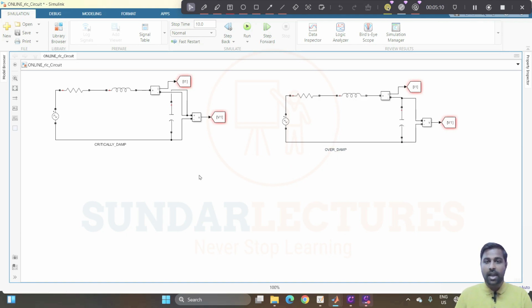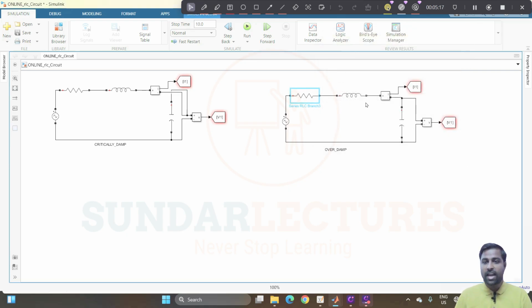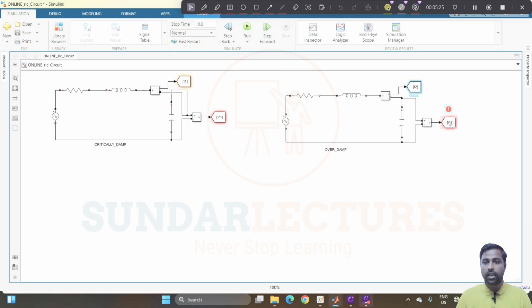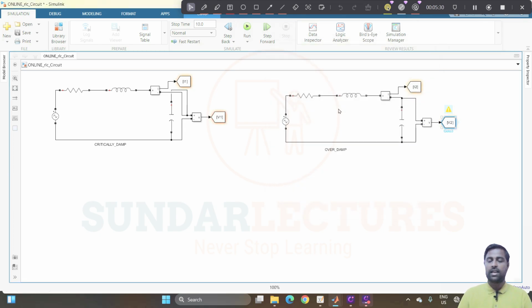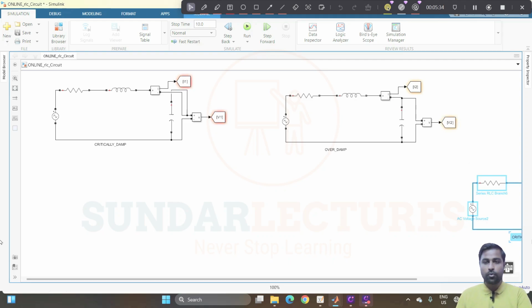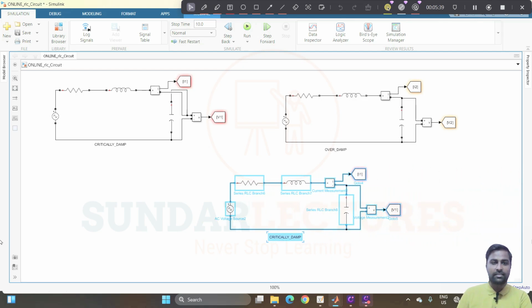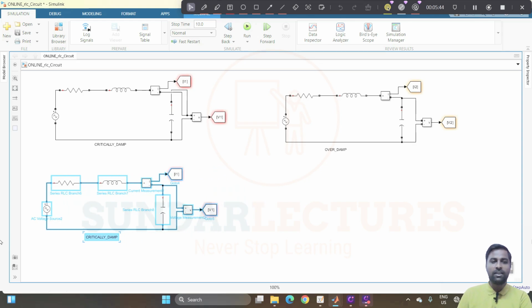this is over damped, and for the over damped, what is the difference? This R has to be 300 ohms, that's all, that is the only difference, and this tag should not be the same. So you take it as I2, click OK, and this tag has to be V2, that's all, right? Now again you just paste it out and move this one, because we have 3 cases. First case is critically damped, second case is over damped, and the third case will be under damped, right?